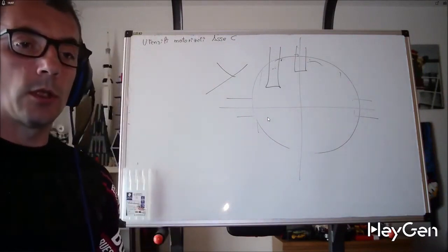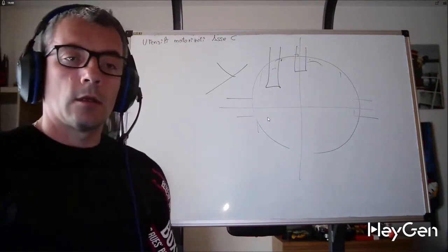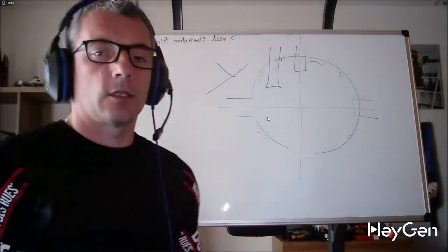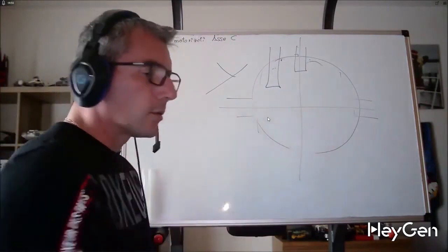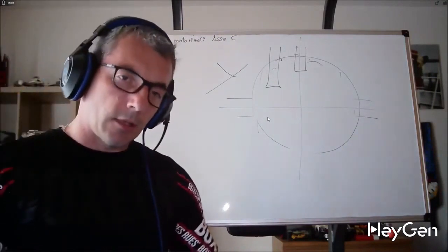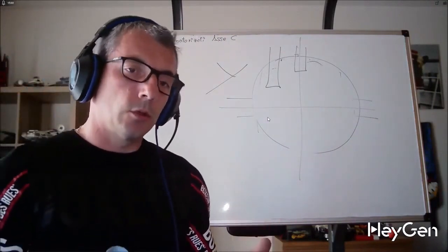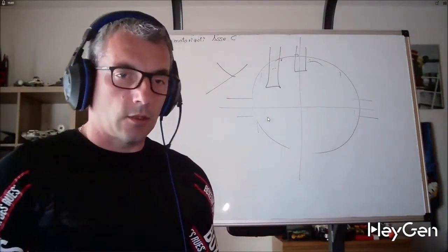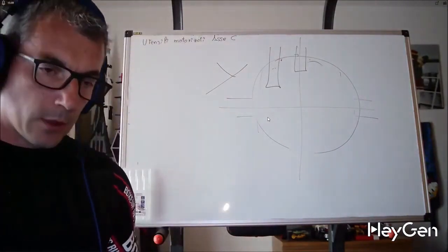The cycles are pretty much the same as what I explained in turning, because fundamentally there's drilling, tapping, and contouring. Nothing absolutely difficult. If you followed the two-axis programming well, you're already capable of doing three-axis programming with a manual.